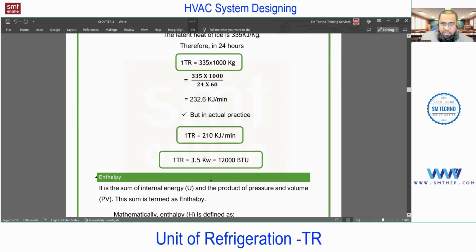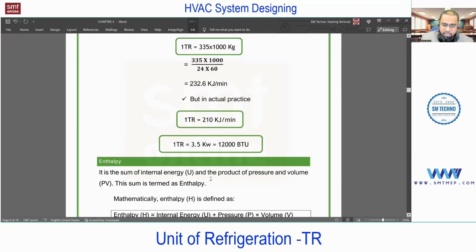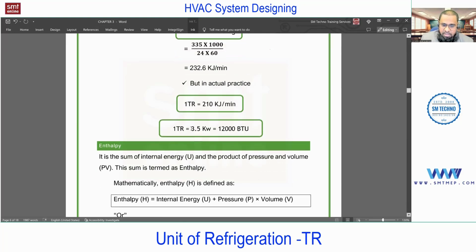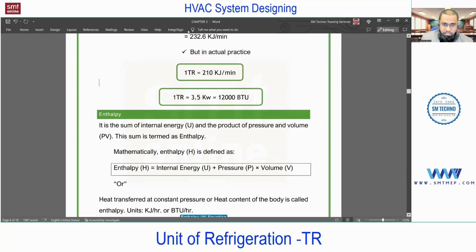Okay. So we have a range from 0.8 to 1.5 kilowatt per ton for the electrical side, but that depends on the efficiency and other factors. But this is fixed. This is a conversion: for a 1 ton machine, how much electrical capacity is required? 0.8 to 1.5 in between, depending on the efficiency. But don't write that down. We'll discuss this at the time of machine selection. Or from an interview point of view, you can consider 1.2 to 1.4 if you talk about split.